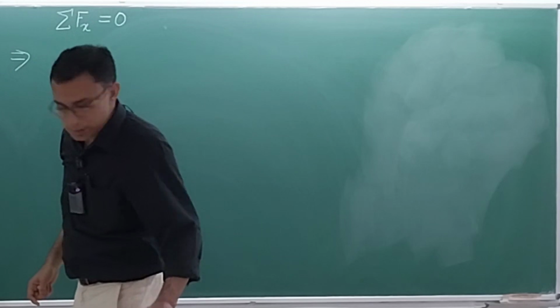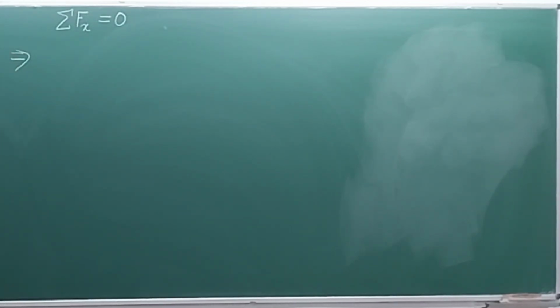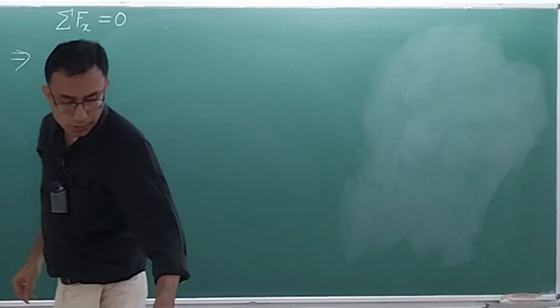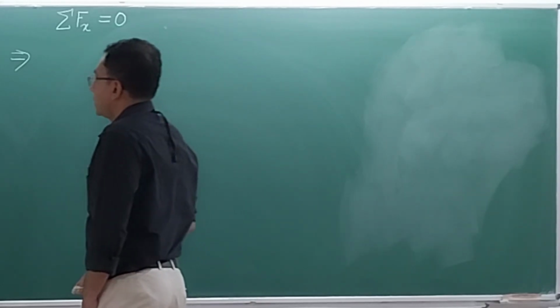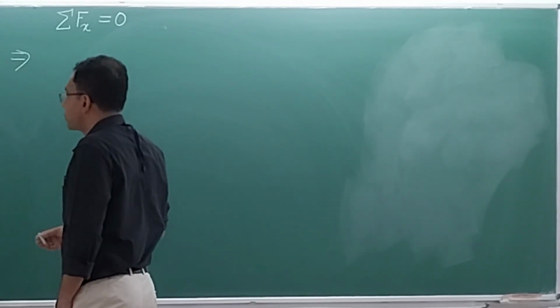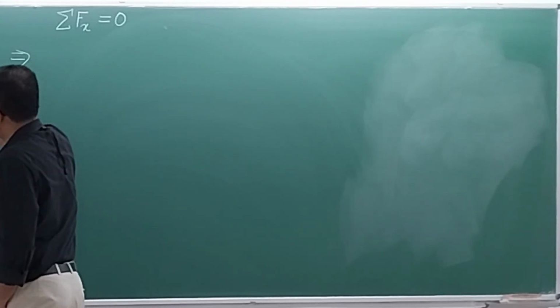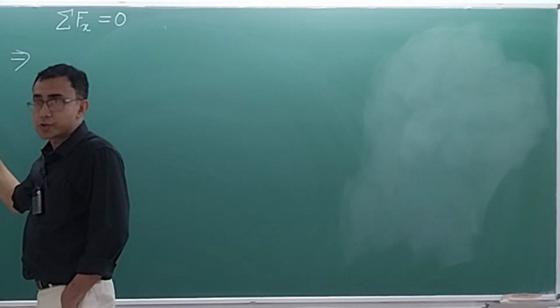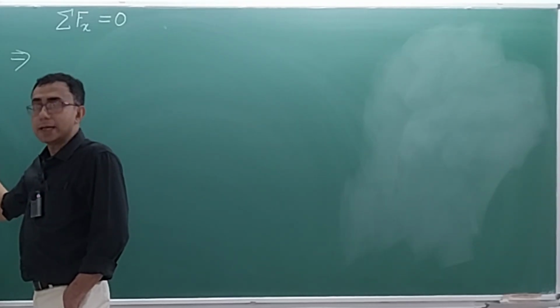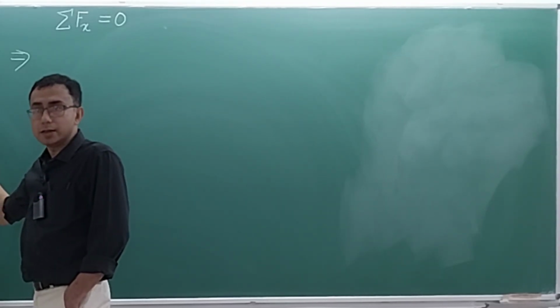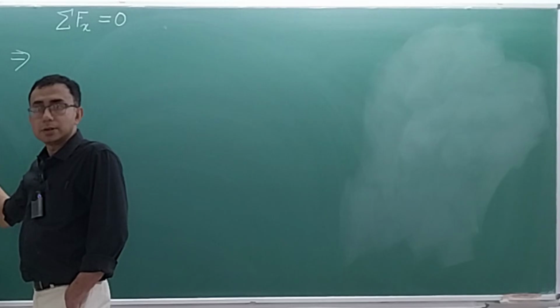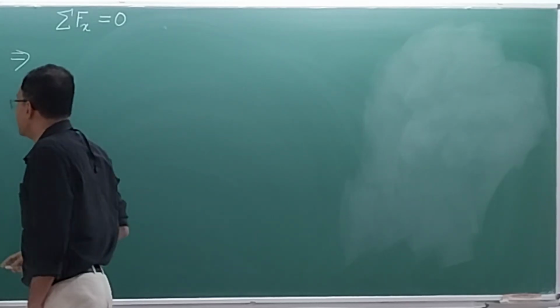By the way, I did not draw this. This length over here, this thing, this is our delta z. Okay. So force balance in the x direction, let's do this one by one. This component of stress, in order to make it a force, I have to multiply by a certain area. What area is that? Delta z, delta y. Okay, very good.